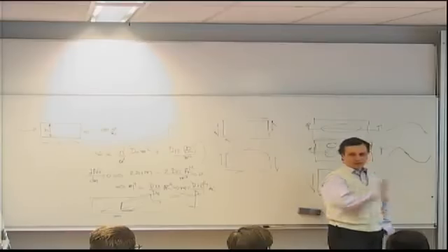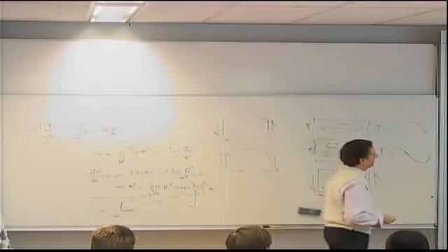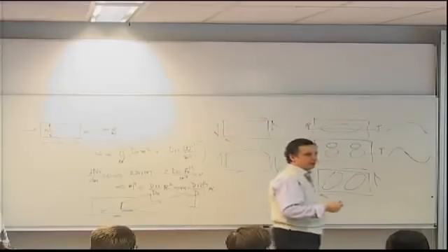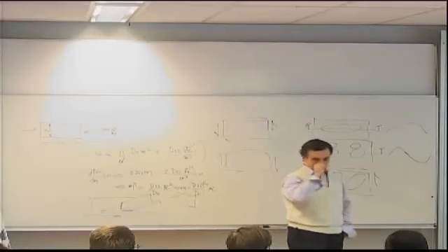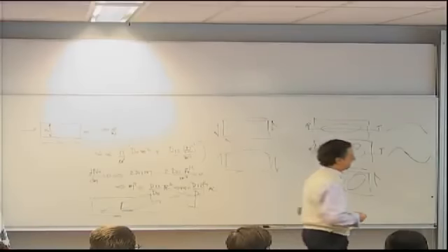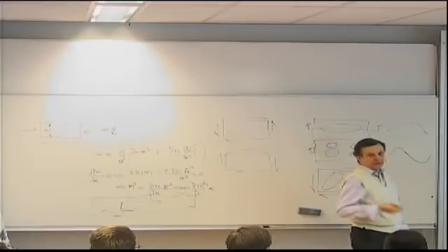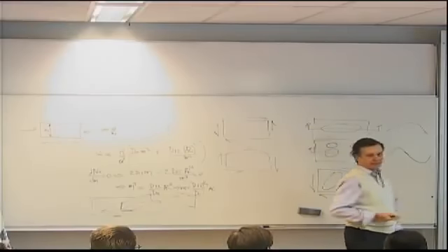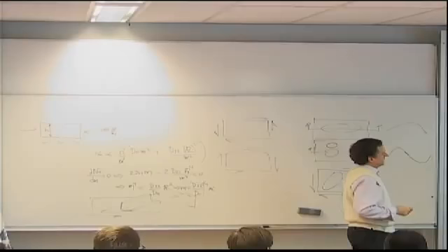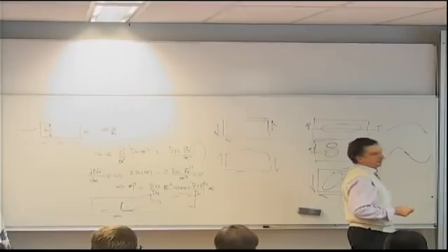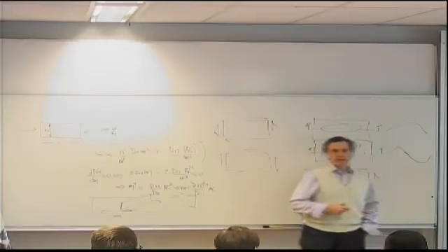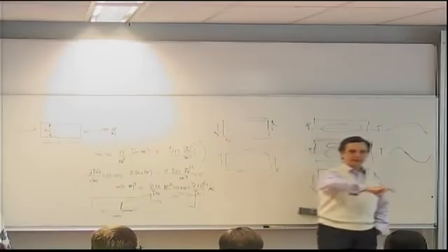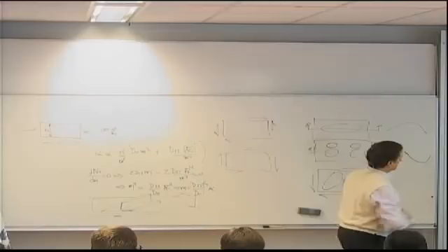So that's a problem. If you're trying to solve a problem of n equations in n unknowns and everything is multiplied with those unknowns, then you cannot solve it exactly. You cannot find them. Basically, they are linearly dependent. The easy solution is W1 equals W2 equals 0, which simply means that there are only in-plane deformations, there is no buckling, and that's the one we are not interested in.